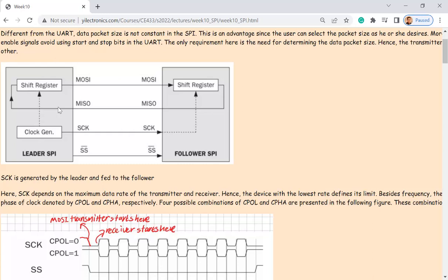So SCK is a clock. The light data will be converted into SPI protocol and sent to the master through the MISO pin. It's the same pin, the same wire. You connect the two pins of the master and slave together, just using one wire. However, they do have different scripts inside, and you do not need to program or modify the module script on the sensor, and you cannot. It's already a hardware. It's designed by the engineer of the company.